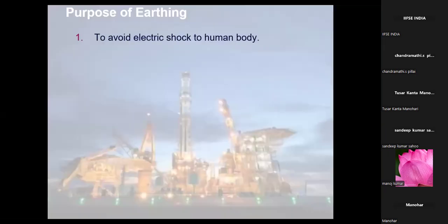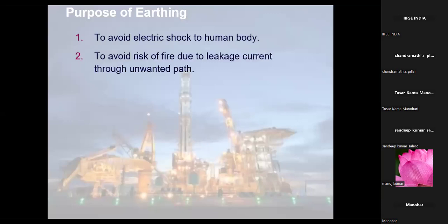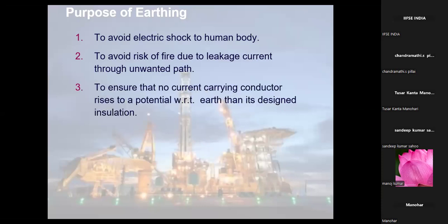The main purpose is to avoid electric shock to the human body, avoid the risk of fire due to leakage current through unwanted paths, and to ensure that no current carrying conductor rises to a potential with respect to the earth, that then it is designed for the insulation.